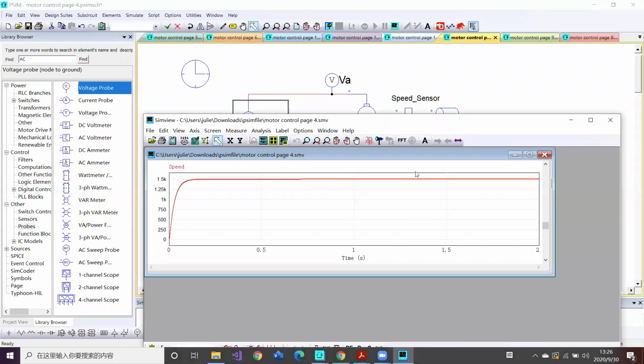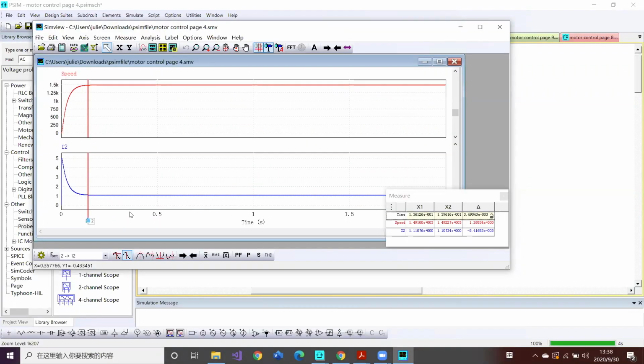And for the TR, what I measured is 141 milliseconds. And the IA I got is 1.1 mA. So any value you get close to this is correct. It's all based on your measurement. Okay, so after this, we will move on to step 2.